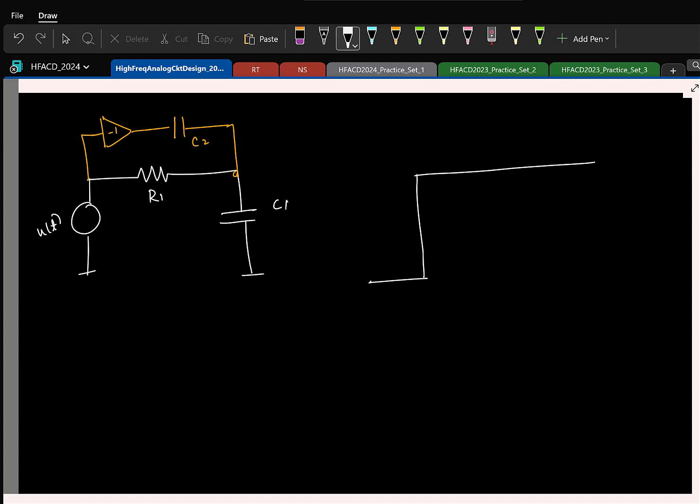Yeah, voltage division. Again, same thing, right? I mean, you have C2 and R1 in parallel. Which of the two will dominate at t equal to 0 plus? C2. So R1 I can ignore it. So I can redraw the circuit like this. Yeah, exactly. So if you will have something like this, you're no longer applying the step u of t.